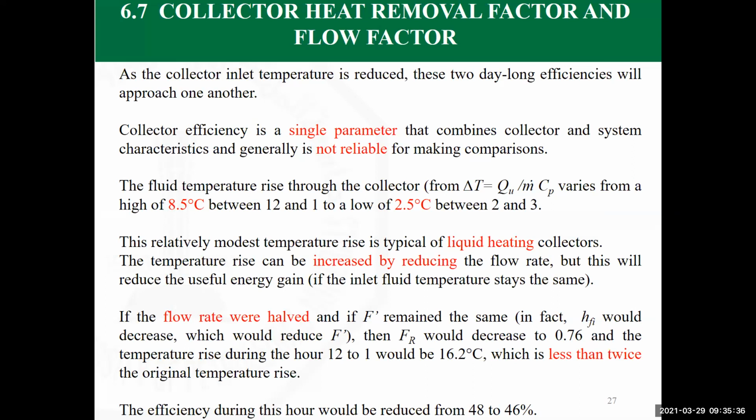The water passes by the heat exchanger and we bring air, usually recirculated air, to pass by the heat exchanger to be cooled, and the air is distributed to different rooms in the building. But the medium that we have selected to bring the cold water from the AC unit, which is somewhere at the corner or outside the building, to be distributed to every floor, we selected water. Because water is flowing in small pipes, it requires lower pumping power, and it keeps the energy with it, whether it is high temperature or low temperature.